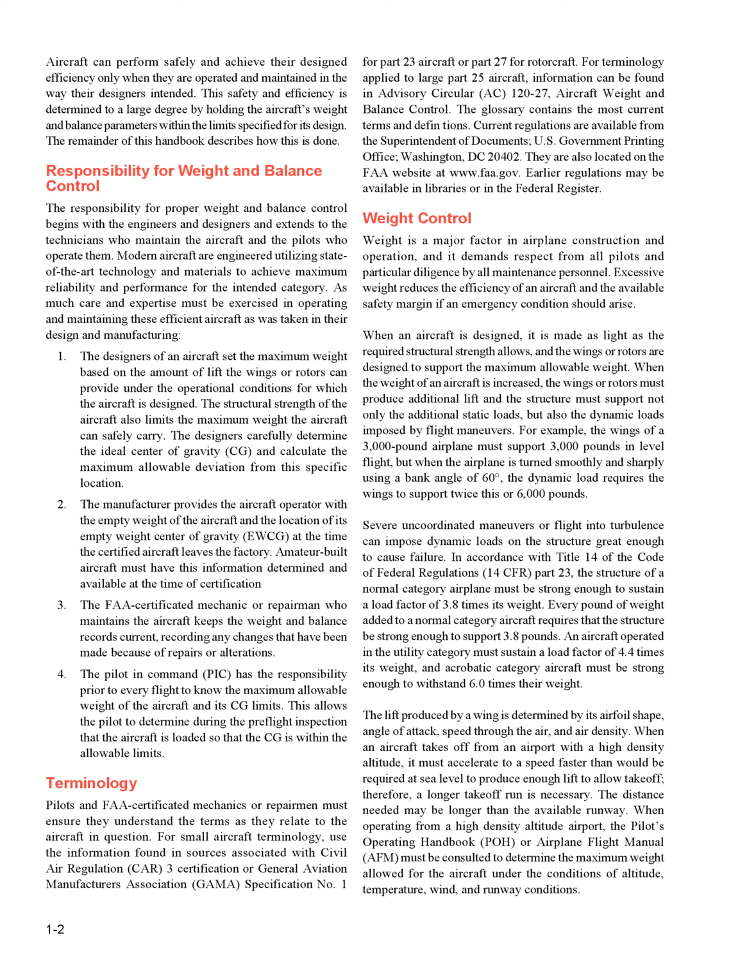When operating from a high density altitude airport, the pilot's operating handbook, POH, or Airplane Flight Manual, AFM, must be consulted to determine the maximum weight allowed for the aircraft under the conditions of altitude, temperature, wind, and runway conditions.